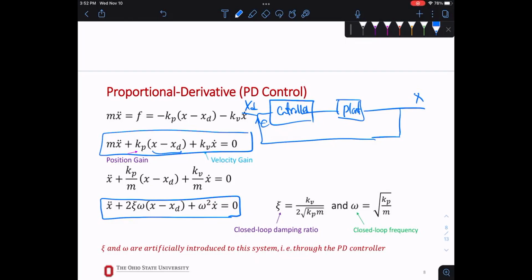What do you know about the motor? Well, you must look at the data sheet. They will have the information for you. It's not just the frequency of your system, right? You also will look at the structure of your system. What's the natural frequency of the system, of the arm that is moving with it? So you will probably tell your structural engineer, hey, reinforce it, if you have to use that controller.